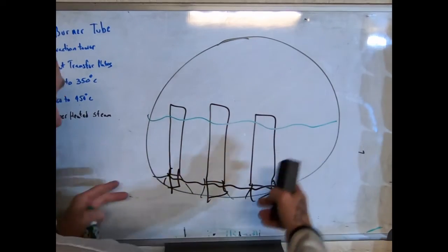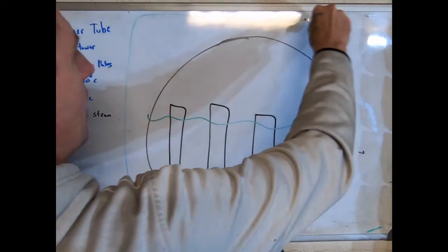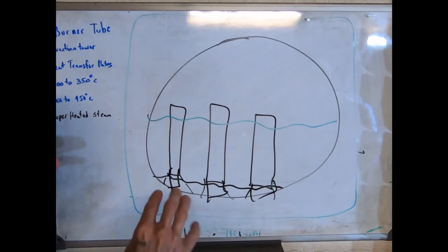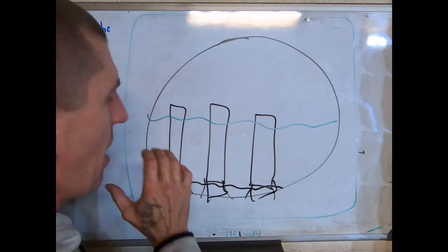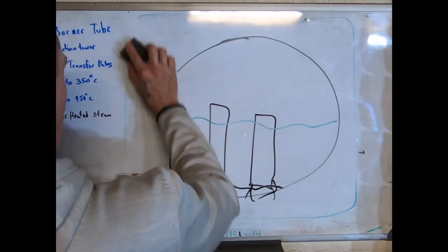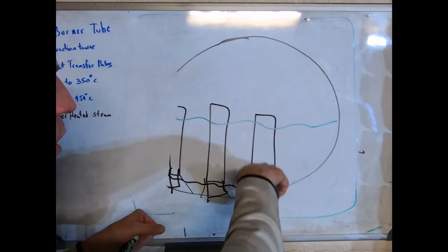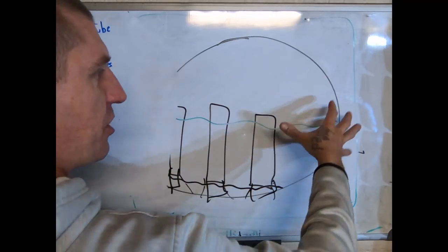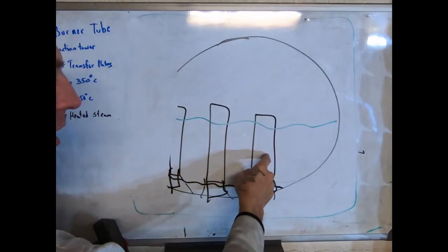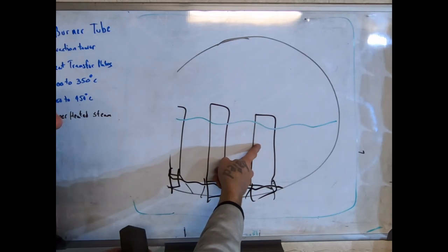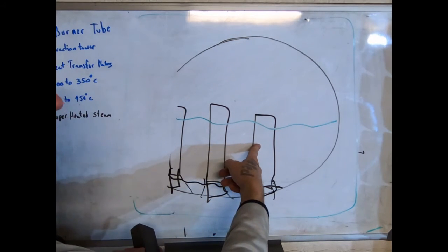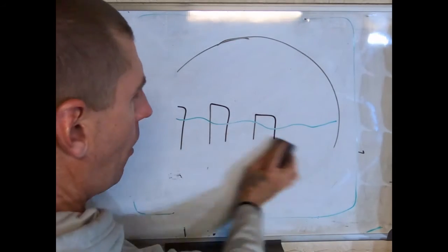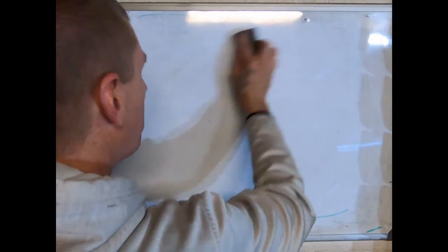I don't like the fact that we're just going to use the firebox as an insulation canister, though, if that's how we're going to do this. I'm not sure what type of insulation you guys have in that thing. Maybe it is okay. I haven't seen it. But this method, this very small temperature junction, is of such that it could allow more heat escaping this tank than we're able to put in it due to the heat capacity of this fluid, which is about 1.8 kilojoules per kilogram, which is terrible. Water's like 4 point something, to put it in perspective.